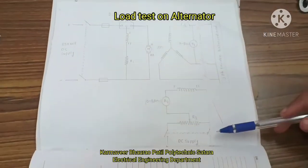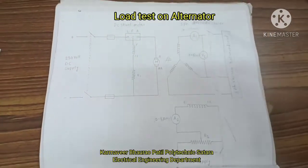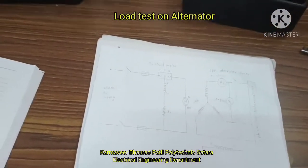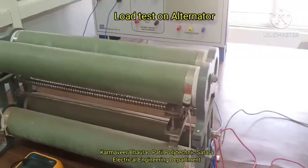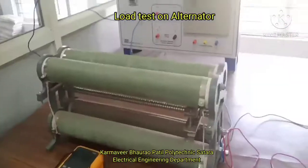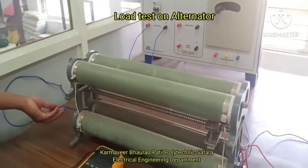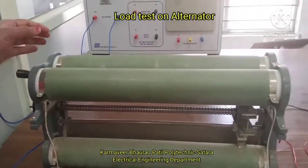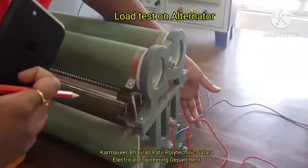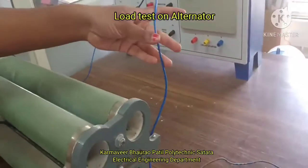Now as far as the field winding is concerned, we are using a potential divider. Supply positive goes to the rheostat fixed terminal on one side. On the other side, supply negative goes to the other fixed terminal of the rheostat.